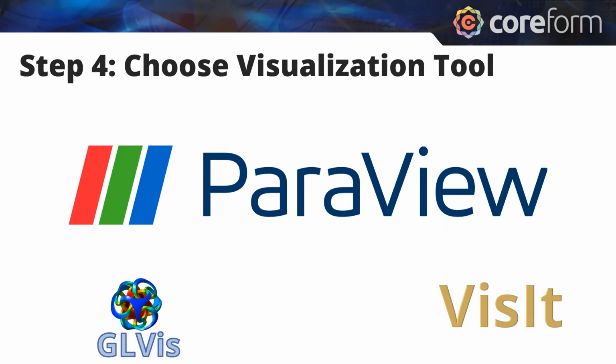There are certain of those solvers that we mentioned previously. There's a solver called MFEM that has a purpose-built post-processor called GLVis. And then there are also certain applications where there's an open source, or at least freely available, code called VisIt from Lawrence Livermore National Laboratory. And you kind of know if you need to use VisIt. So for 99% of folks out there, you can just pick ParaView and feel good with your choice to use ParaView as your visualization tool. You can obviously also write your own bespoke visualization tools in, say, Python with Matplotlib or MATLAB or something like that.